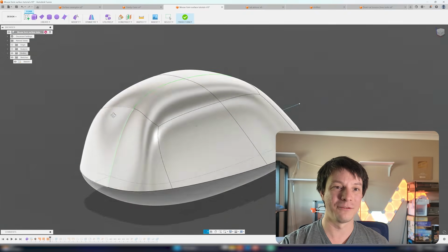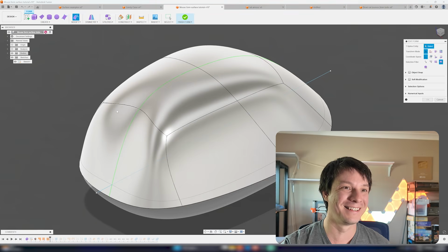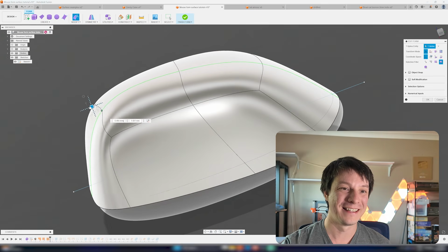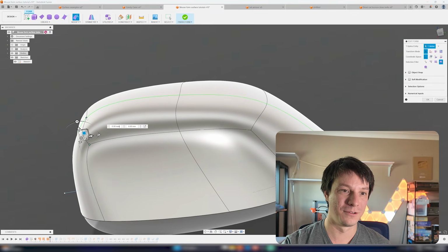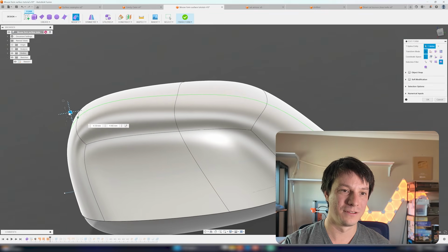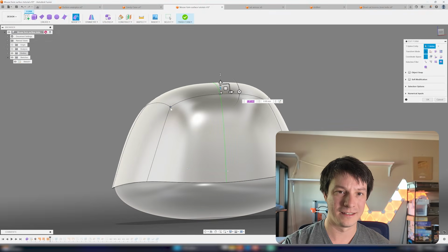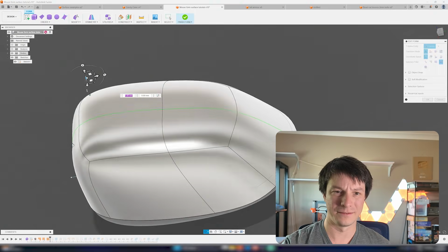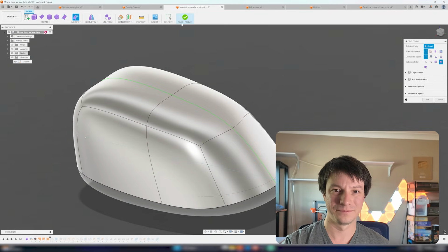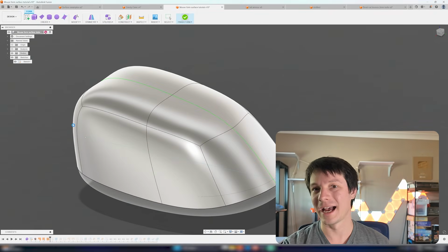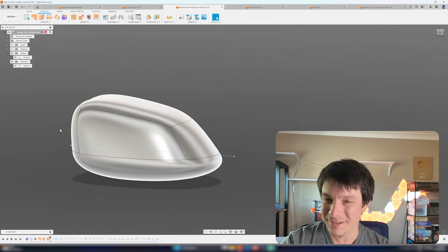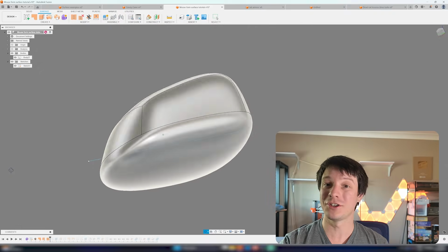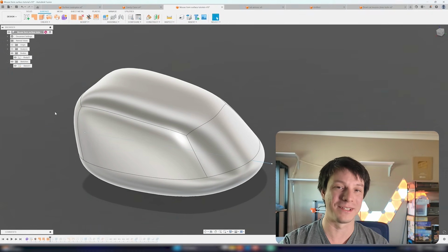We can say, okay, I don't want the back to look a bit like a bum. I don't really want it to have that crease there. Let's pull that edge out like that. And maybe pull this edge a bit up, a bit more. So it's more rounded there. And more like that. Okay, maybe more like that. And I can say, okay, finish form. And as long as you don't change the faces so much that they no longer intersect with the areas they were before, there's a bit of wiggle room. The tools usually don't fail, and you can see it's updated perfectly fine.